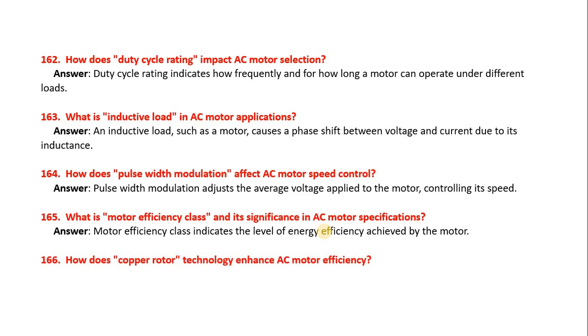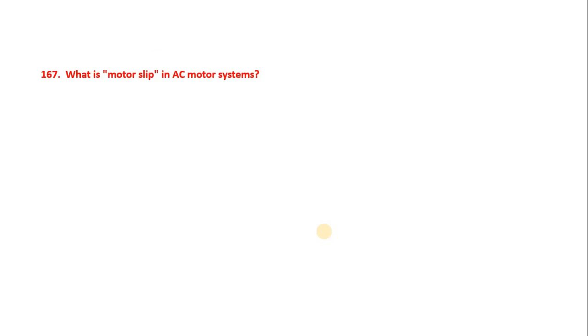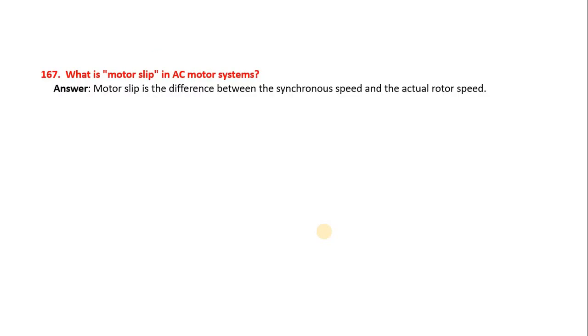And how does copper rotor technology enhance AC motor efficiency? Copper rotor technology reduces rotor resistance, improving motor efficiency and performance. What is the motor slip in an AC system? Motor slip is the difference between synchronous speed and the actual rotor speed.